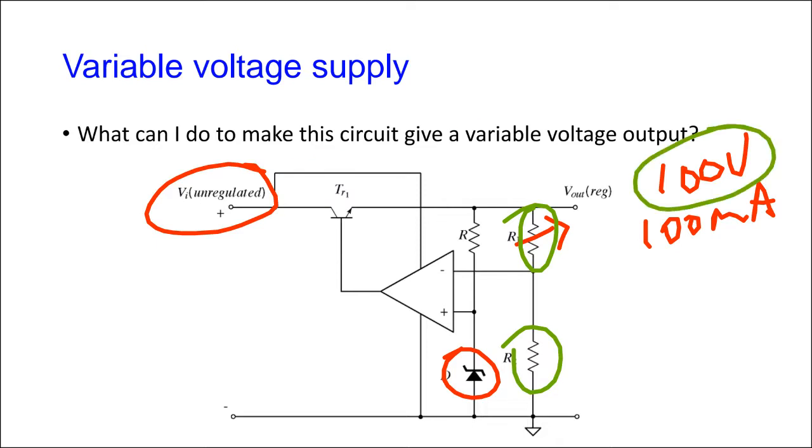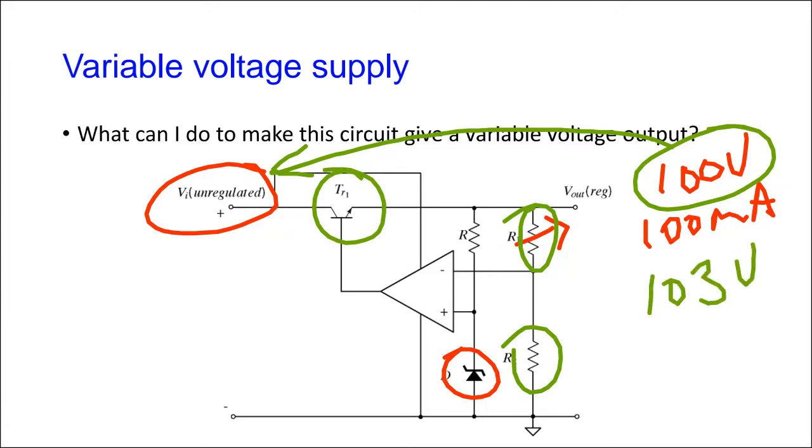Of course, you now have to make sure that you have a transformer that could give you at least, for the transistor here, you need at least about 102, 103 volts DC at the worst case coming out of that. So you have to go back and get the transformer and the filter capacitor and so on. All right, but if you have to design, and there are cases like that, there are motor control circuits and so on that work with high voltage DC.